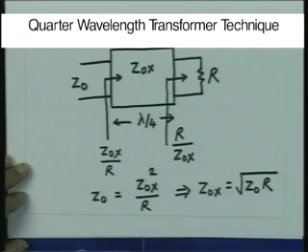That means, if we introduce some section of a transmission line, the same transmission line with characteristic impedance Z0, then the impedance seen at this end of the transforming box will be a real quantity if the length transforms the impedance in such a way that there is a voltage maximum or voltage minimum at this end.